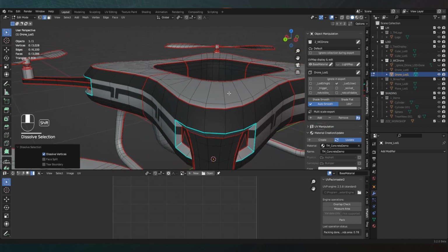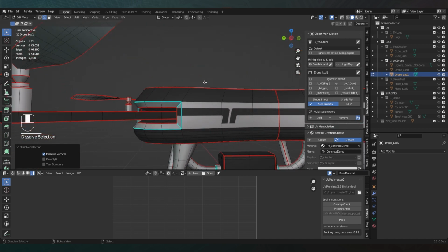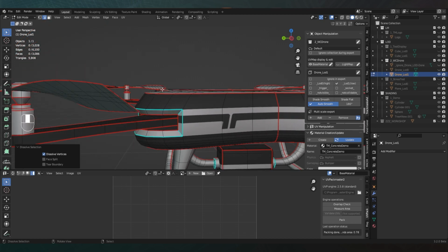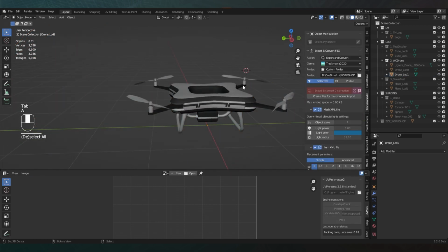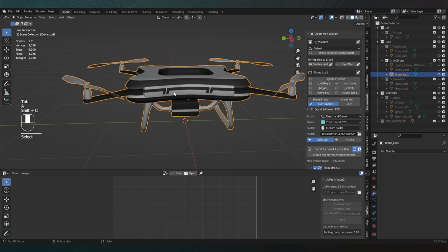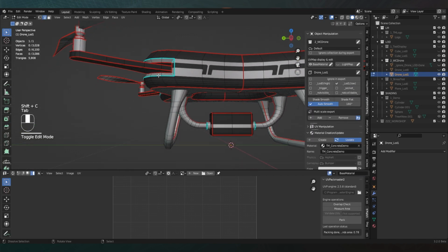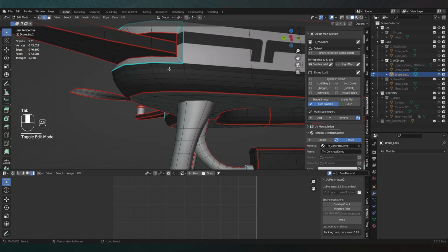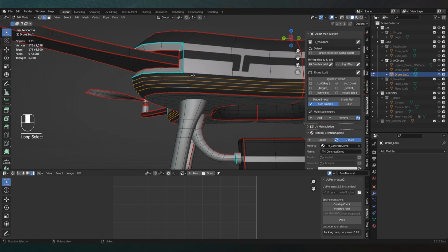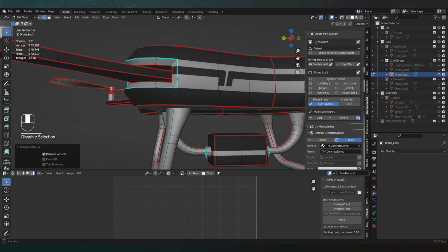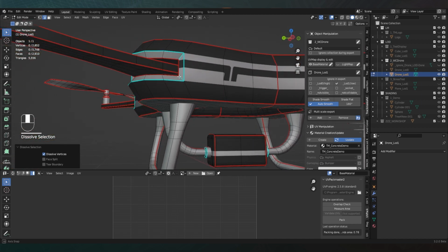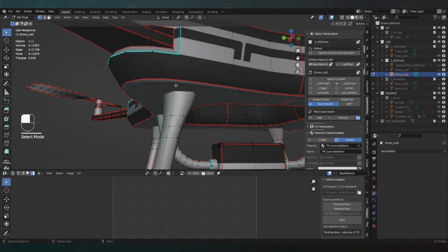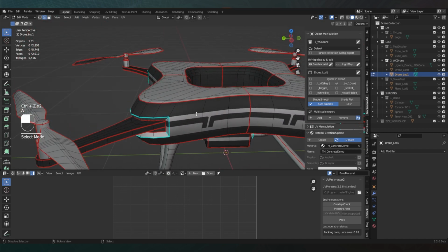Since I'm using the Blender 2.79 controls, my left mouse button is only used for positioning around the 3D cursor, so in edit mode it has no function. So I figured, why not use it for something useful? And I will just select a bunch of edge loops, left mouse button, and boom, it's completely simplified. This also works for vertices. Of course, I wouldn't do it here. And it also works for faces. But yeah, let's concentrate on the edge loops.